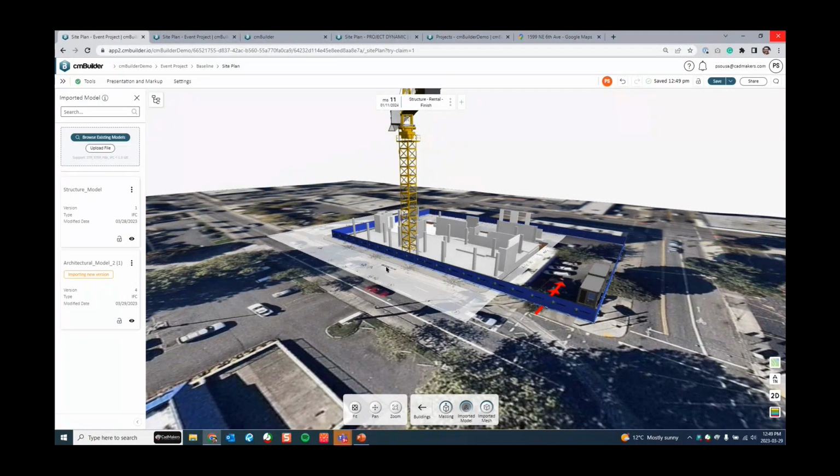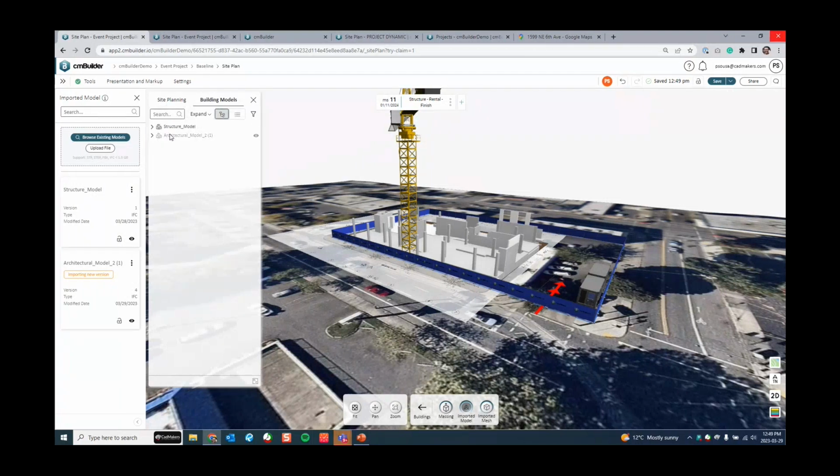So what is it that we are comparing? We are comparing the tree structure over here. These are the two models that I have available, and this tree structure is defined by the source CAD software in which this model was created. If there is a big change, we won't be able to retain a lot of the sequencing. But if the changes in the tree structure are not that major, the geometry itself will be updated and everything will be updated.